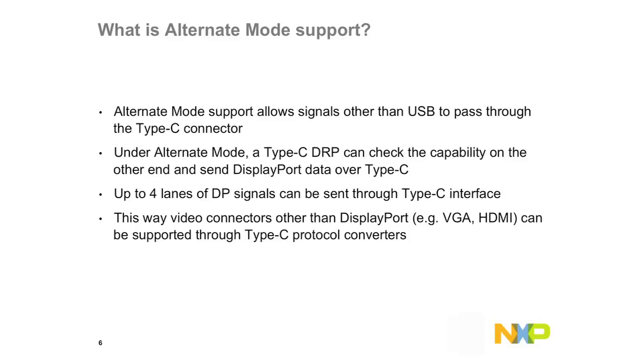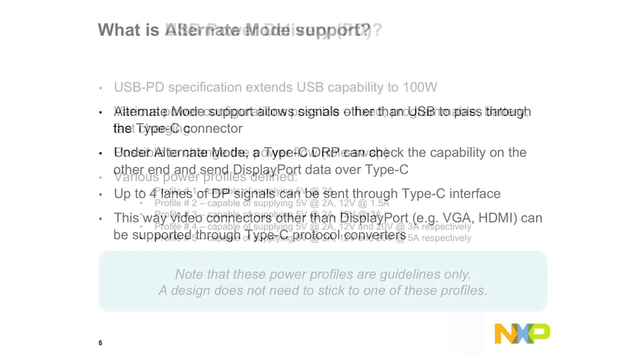One thing to mention, alternate mode is very closely tied with the power delivery spec. So if you do want to support video over Type-C, you need to support the whole power delivery spec from a design standpoint, because that's how the messaging is written in the spec. So they both go hand in hand.